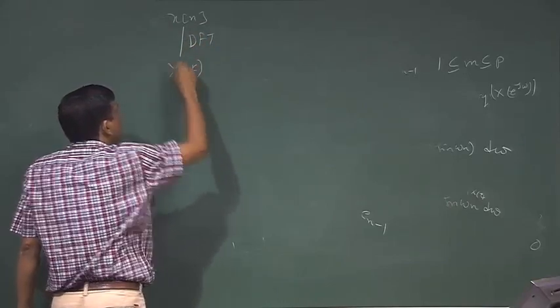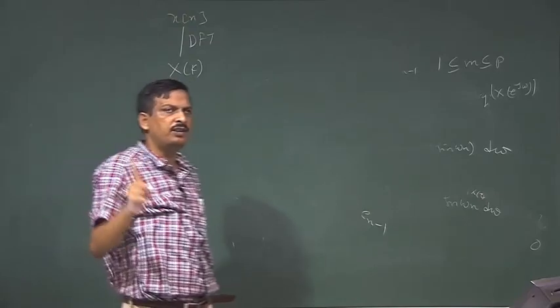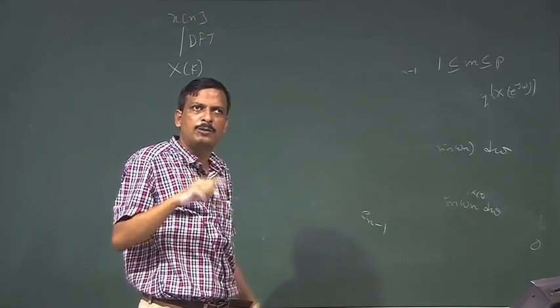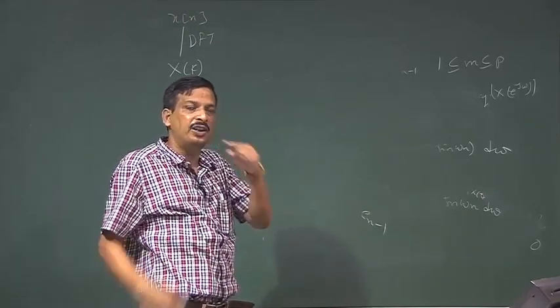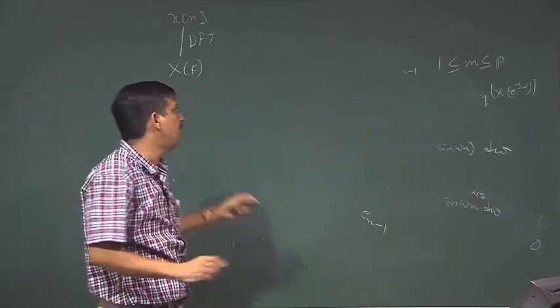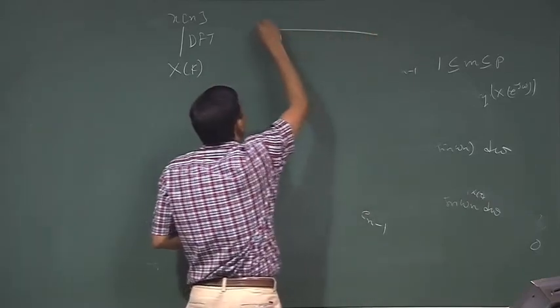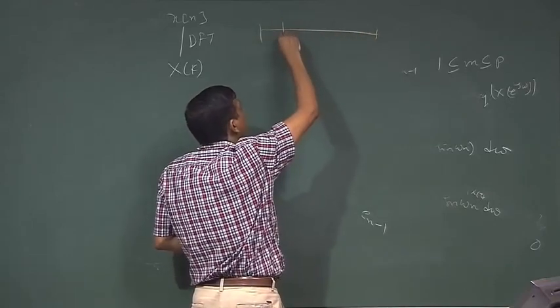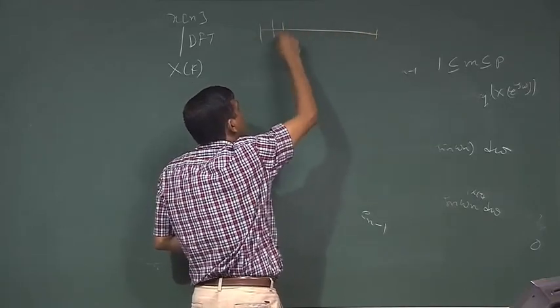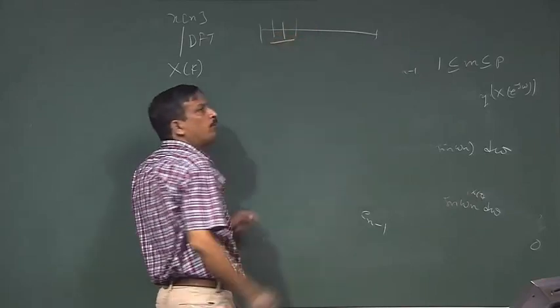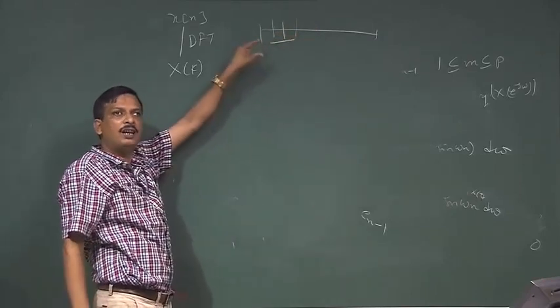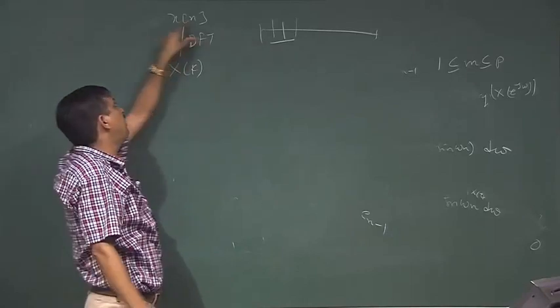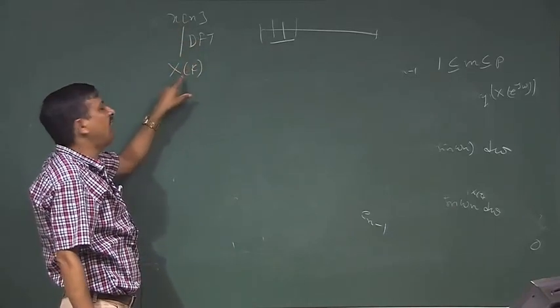I am not explaining framing and windowing, which are also part of speech processing. Instead of taking the whole signal at a time, I pre-emphasize the whole signal, then cut the signal in a frame, in a window, then shift the window by a frame. So, framing, windowing, all things I have done, and after that if I take the DFT, I will get Xk.